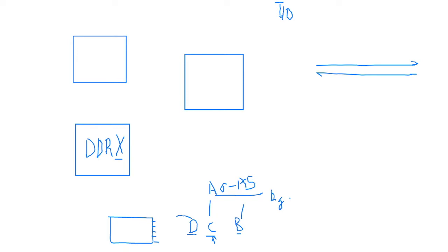Okay. So now we know that port D0 and 1 are used for transmit and receive, and then 2 and 3 go to the interrupt pins. So if I ask you to make use of interrupt, remember you are aiming for 2 and 3. Now, at the same time, in our circuit, we made use of pin 2, and then we made use of pin 5. Anyway, so back on here, it means we are interested in data direction register D.